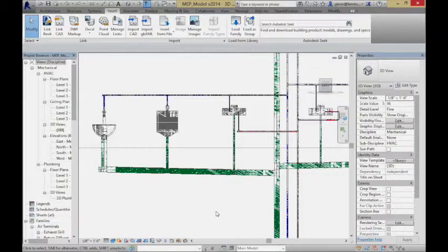But as you have smaller pipes joining in, you have all these funny little connections, little T's, where you have to get all the different pipe connections fitting together. The other thing you'll notice is that the lateral isn't horizontal, it's actually sloping. It's important that from the end, moving towards the center, it has a little bit of slope so things run downhill. That's basically how sanitary systems work.